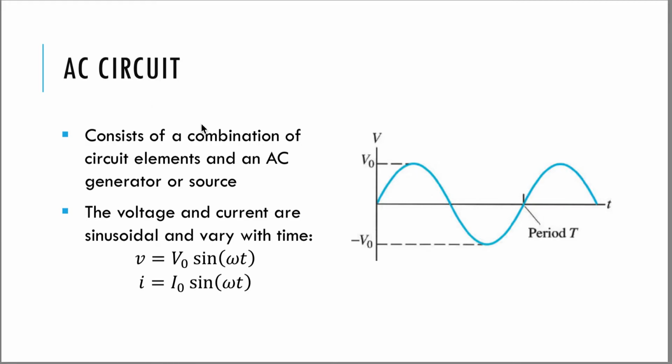So an AC circuit is simply a circuit that is going to have an AC source and whatever elements you want to put. We'll start off with just a resistor and then add capacitors and inductors. You can use a sine function to represent AC current and voltage. This sine function is the same thing that we learned about with generators: generators generate an oscillating, alternating voltage. What this sine function shows is that at one moment you've got no voltage. You could have the same function for current; you can pretend this has current instead of voltage.